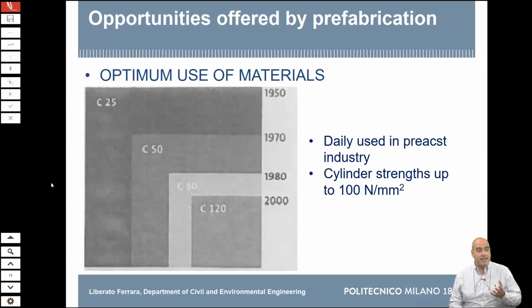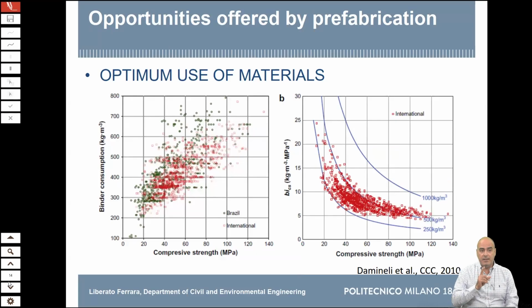But then the technology evolved. Now, if you take, for example, the Eurocode or the fib Model Code, there are classes up to C100, 110, or even up to C120. Very high strength concrete, ultra high strength concrete and so on. But this means very, very precise quality control. Also, in precast concrete, you can rationally handle the seasonal variations, because casting in summer is not the same thing as casting in winter and so on. So this is something that you deal with in the precast concrete industry. And the other thing is, let's always think in an engineering way, engineering-wise.